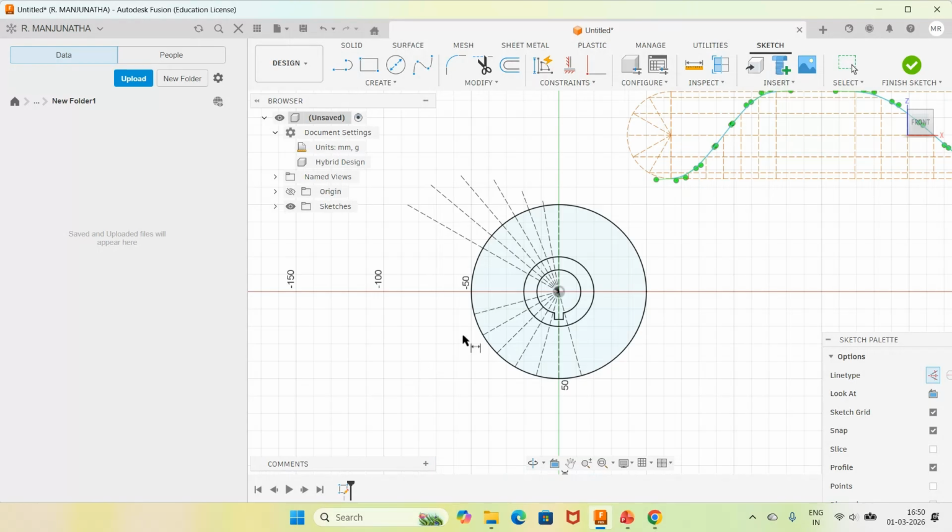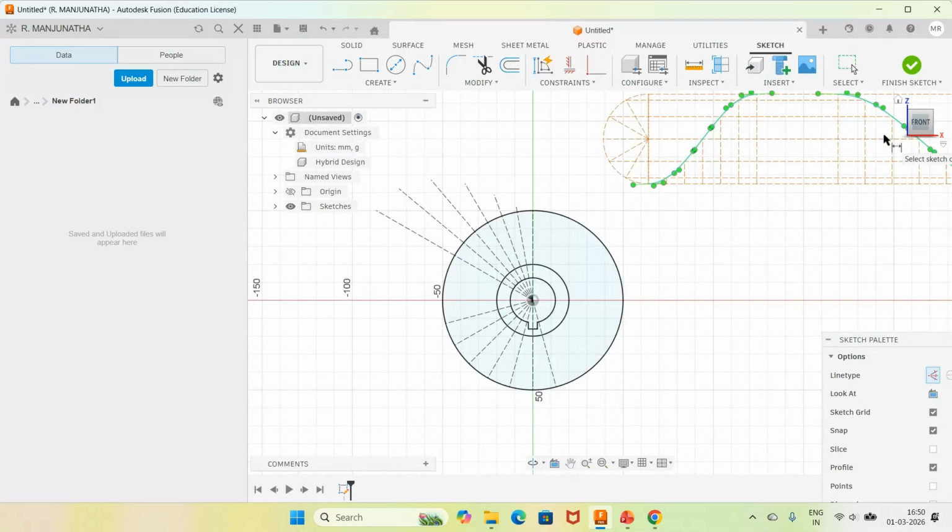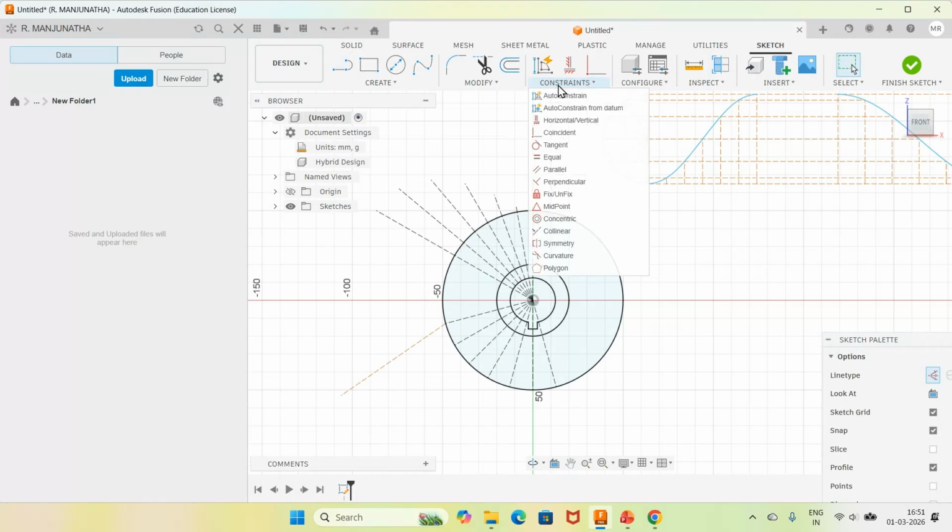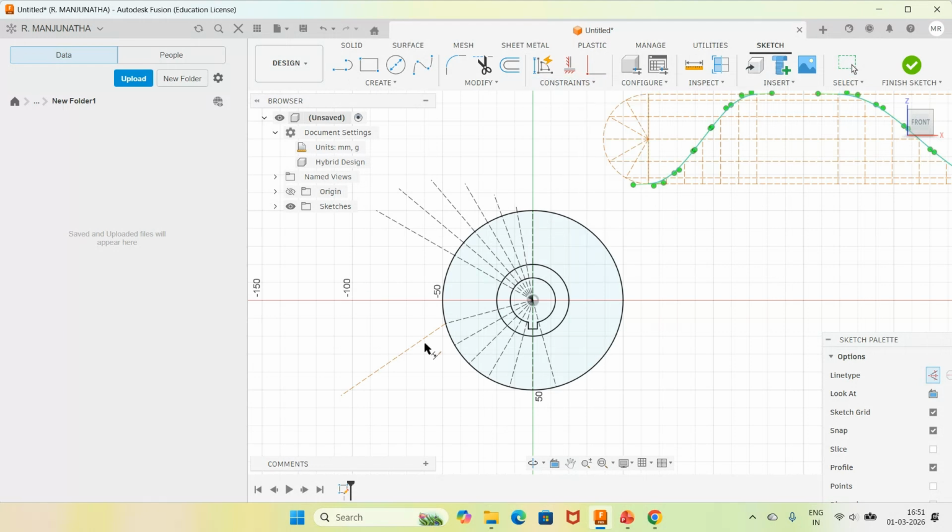So similarly, at this particular point also, you will have a lift of 50. So now what we have done is we have gone from 50 mm to 100 mm. Now we want to maintain the same thing from here to here. So again, I will go for line, select some arbitrary point and then drag a line here. Then you go to collinear, select between this and this, and go to dimension, select this, go to measure, click on this line now and press enter.